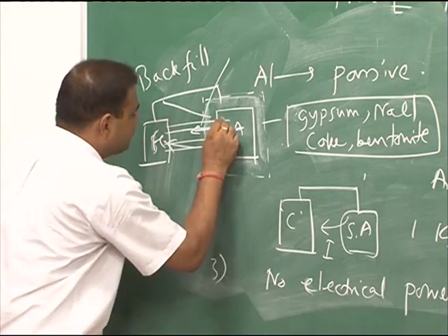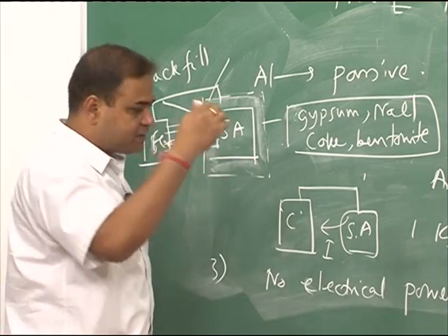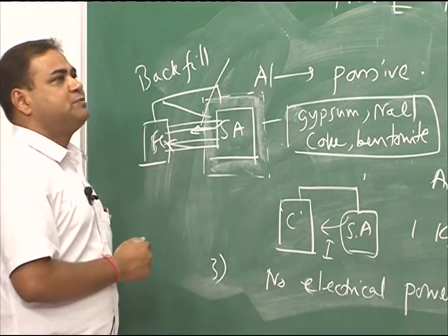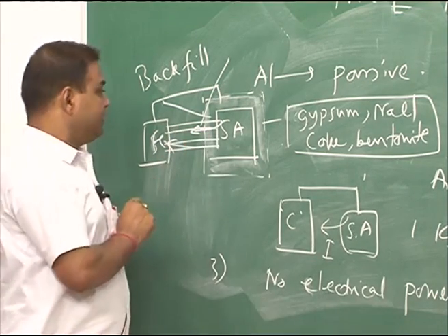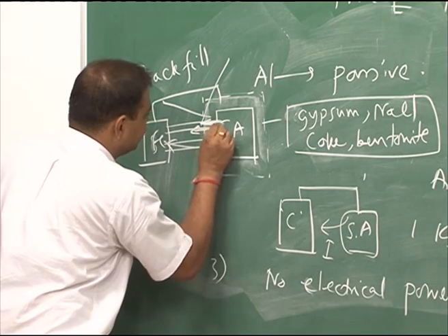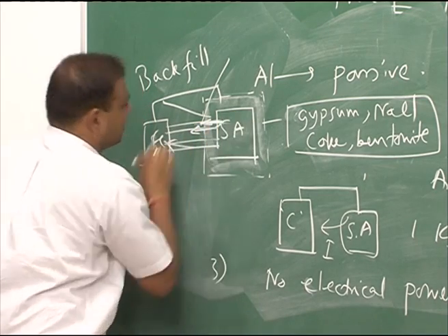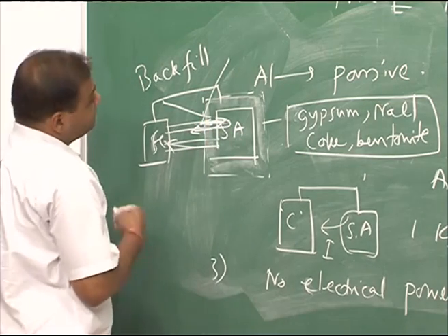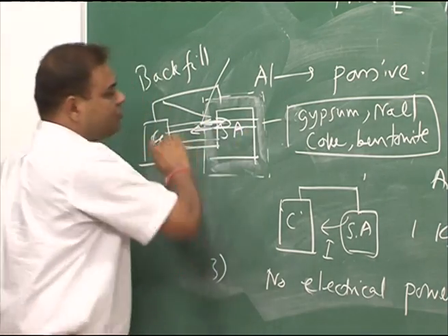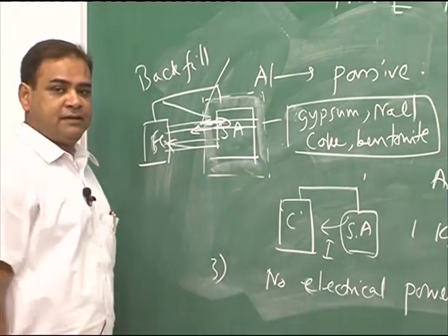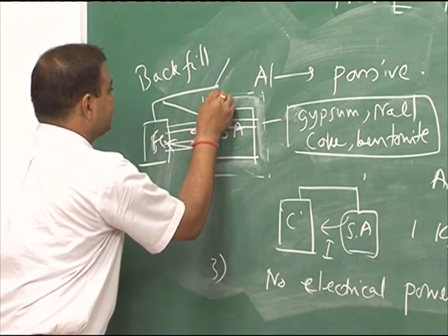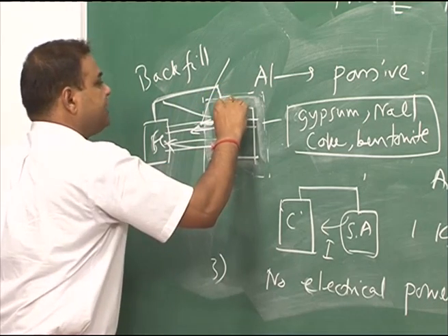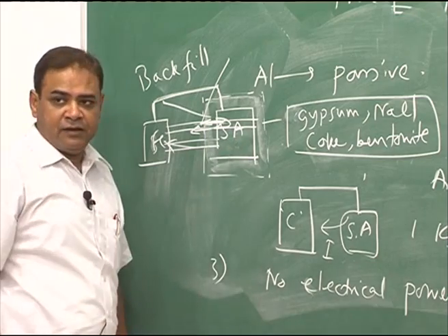We have seen that wherever the current is coming out from the anode material, that part will be corroded. So, the current is preferentially going through this particular part. So, we have more corrosion here. Now, it may happen that this entire part will be corroded and the lower part is detached. But the electrical connection or the conducting wire is connected on top of this, so only this part gives the protection, and this part is invalid.